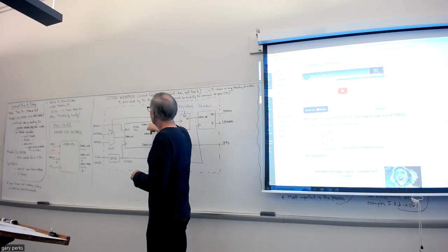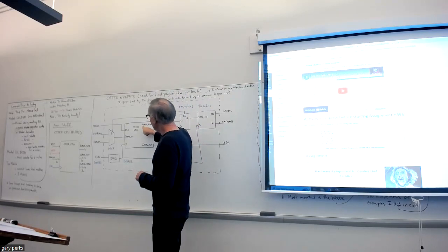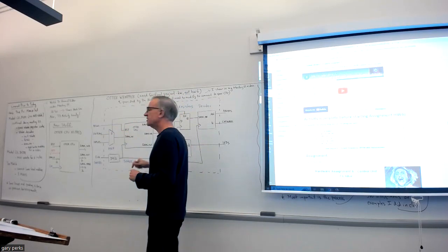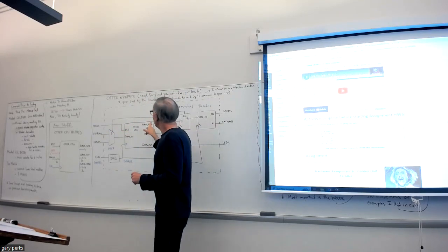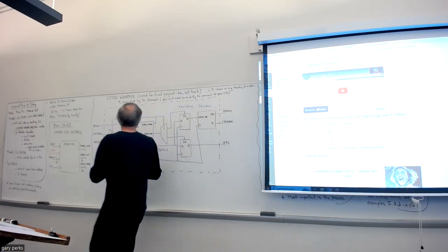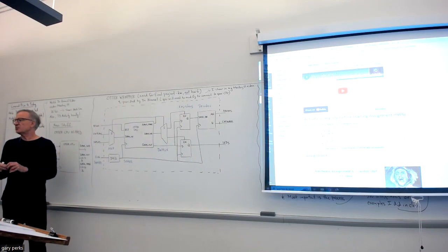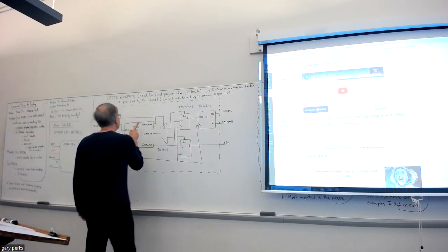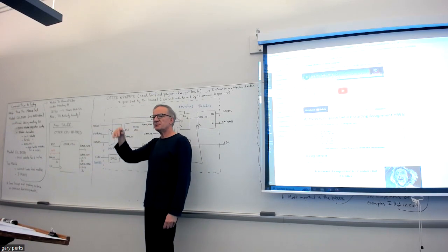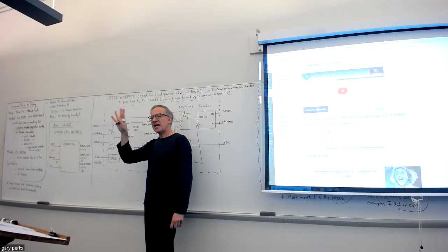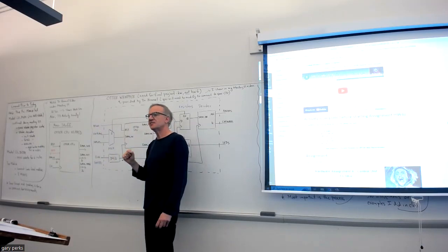Now, a good thing to notice here is, see this IO bus address? It connects to the selects of the MUX and the DMUX. So this IO bus address is going to be the addresses of your input devices and your output devices. So for example, when you have some instruction dealing with switches, do you remember what address we're using for the switches from your assignments?